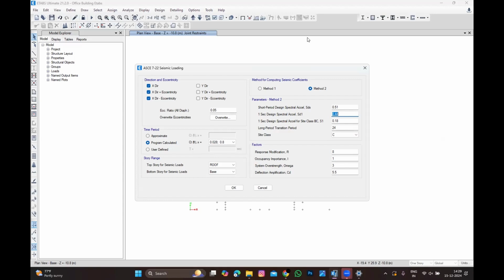You can use 4.5, because you have so many columns. See, I'll tell you the difference. Shear wall system is 5. Pure column frame system is 4. The column and shear wall together is 5. That is 100% correct. But in recent DM actually they want us to go for 4. Okay, you can still use 5.5. I don't want to confuse. Still you can use 5. No problem at all. But use 4.5.